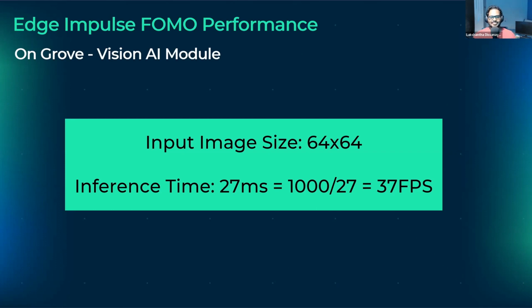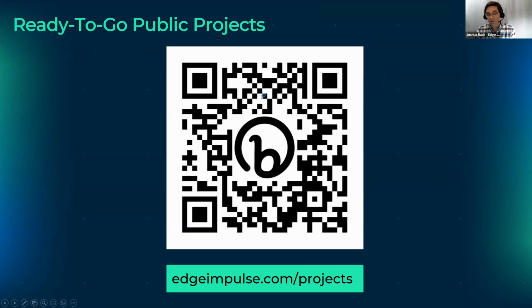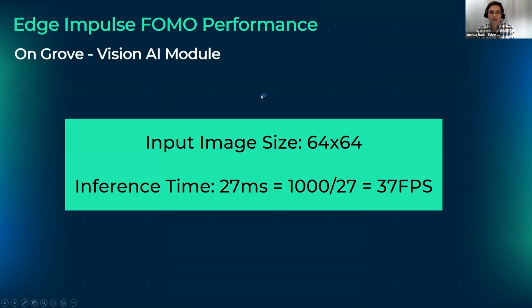Yeah, typically for embedded applications, you may not be displaying over a serial connection to a web page. Exactly. And in that case there's an Edge Impulse SDK which you can use, again with the same model, to run the classification or run inferencing function, from which you get the output, the confidence intervals and the different TensorFlow outputs that you need in order to make a determination of what exactly you're looking at.